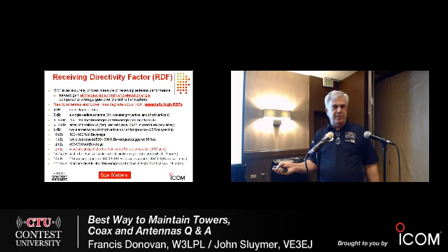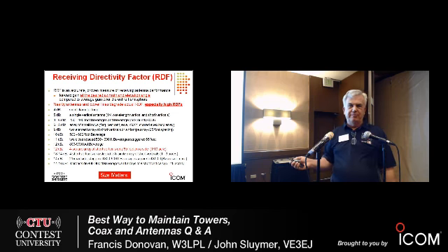Now here's a real sweet spot. And for anybody thinking about receiving antennas, this is a relatively compact antenna that offers really high performance. Look at that number. It's right up there among the very best antennas you can build, including an antenna that takes 20 acres. Just a few dB down. A 4-square array of short verticals, about 65 feet on a side. So that's a pretty small piece of land, about 1/10 of an acre. Offers very high performance. I'll show you a couple of alternatives for that.